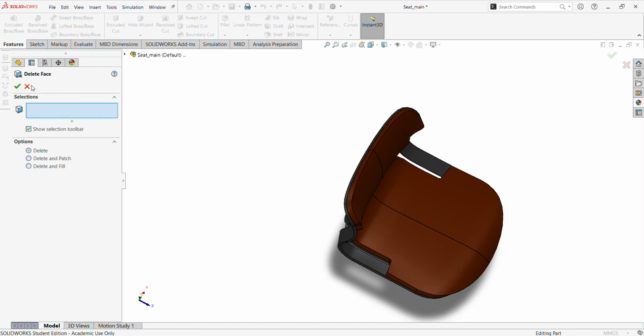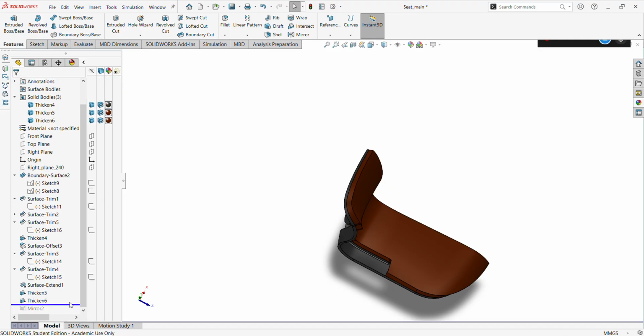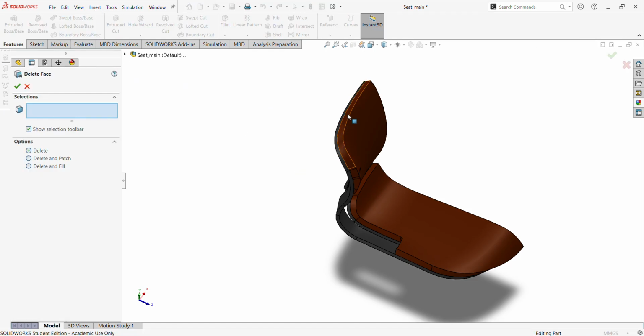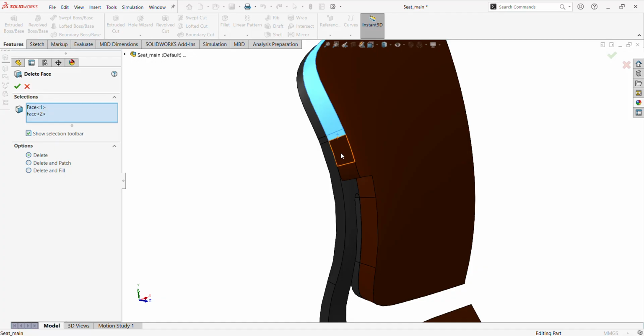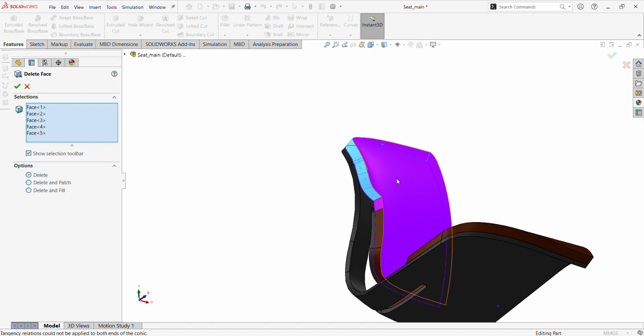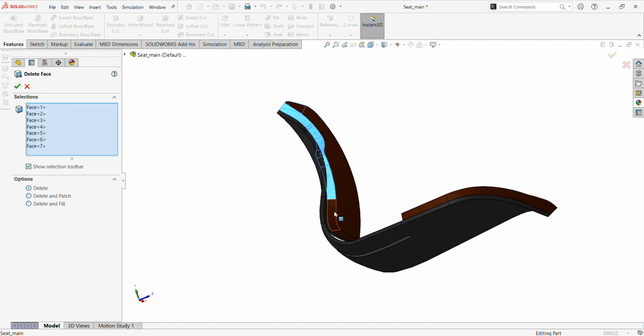But before we do the face delete, let's do something. Let's remove the mirror. So let's shift up one step upwards, and then let's redo the mirror. We'll redo the mirror, but let's not split the face using what is called a face delete. And then we want to split, remove this face, remove all these faces. So you can select with automatic here, or you can also select random faces, but let's just do it manually for the purpose of these tutorials.